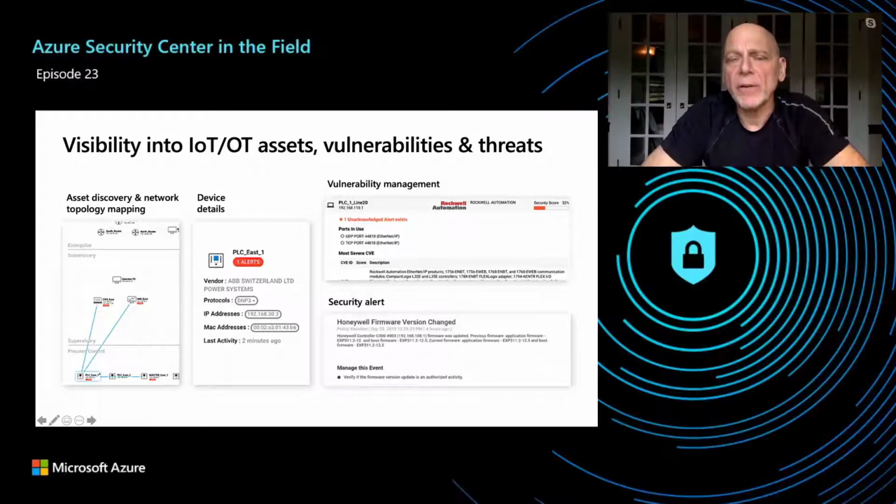And usually we see a hybrid. We see, for example, some of the people in the plant might be monitoring the alerts related to operational issues, like if equipment has been misconfigured or is malfunctioning. Those alerts will typically stay at the plant level because they're more operational than cyber. But then typically what our clients will do is they'll forward all major and critical alerts into their SIEM because they need to be investigated by their security operations team.